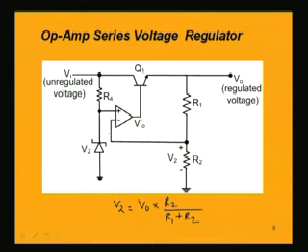So Vz minus V2, this voltage is the differential voltage available at the input terminal for this op-amp. So the output voltage V0 dash is nothing but the gain of the op-amp multiplied by the differential input Vd, which is Vz minus V2.